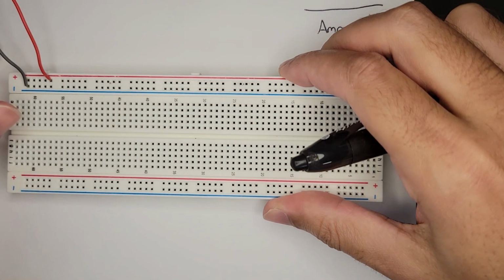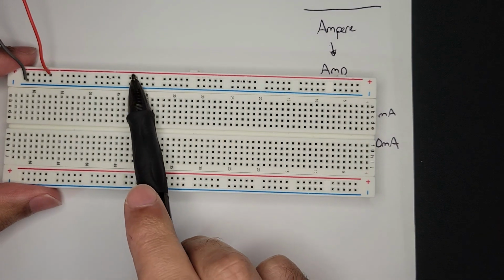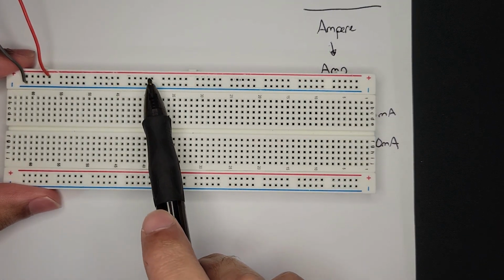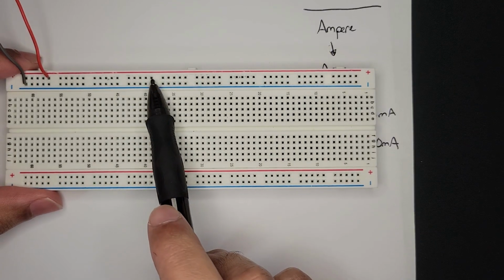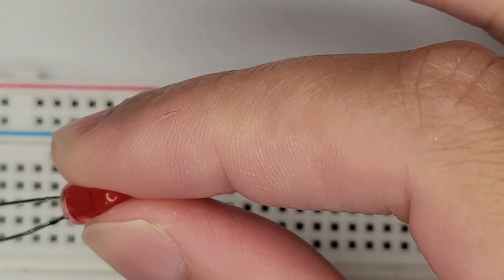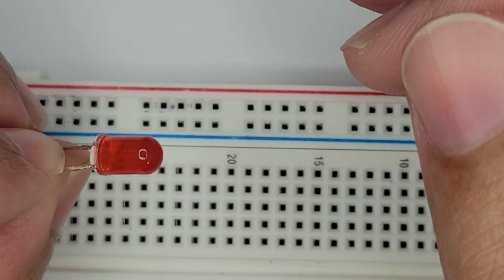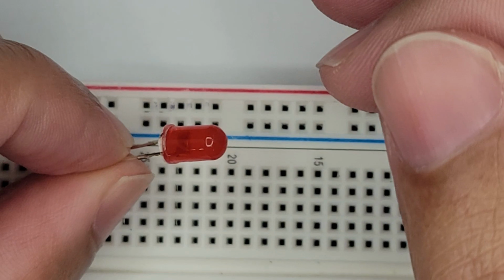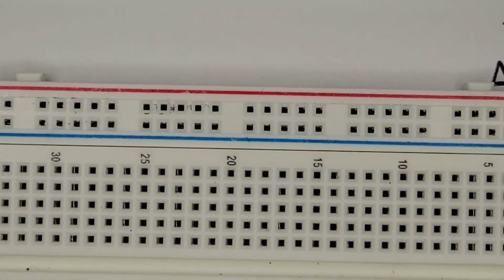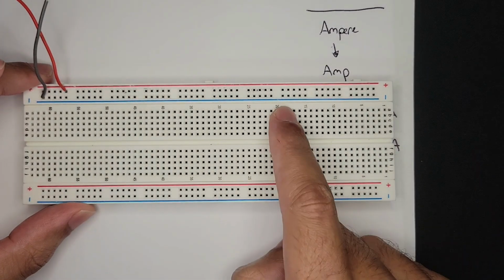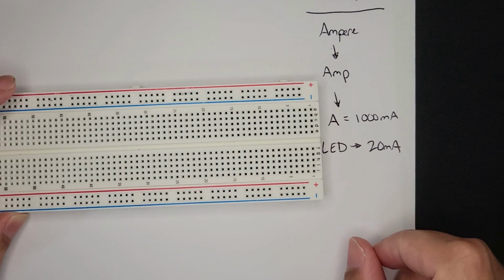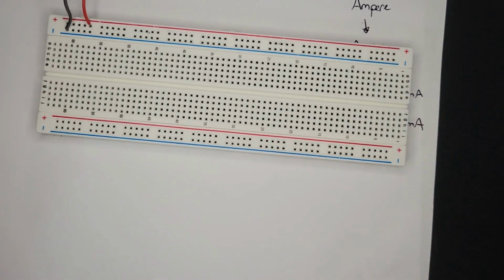So with that said, we know that if we plug this into our power source, we have 3 volts coming through here, as well as 2,000 maximum milliamps. So if we were to plug in our LED, then the LED would probably explode because it's 100 times more current than what it wants. So what we need to do is figure out how we can reduce the current here from 2,000 milliamps down to 20 or less than 20. And the way that we do that is through resistors.